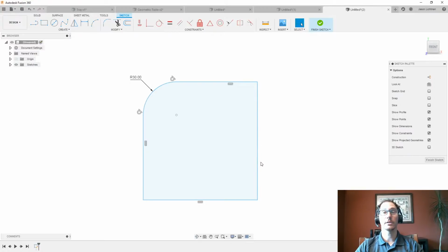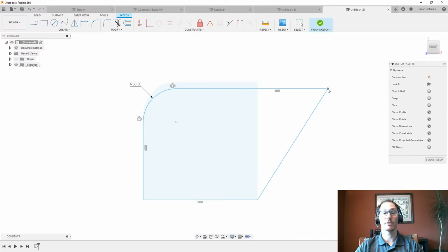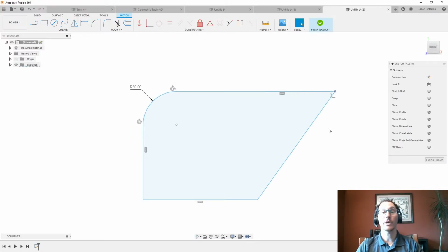Once it's deleted, the geometry itself isn't fully defined anymore, and now you could go and modify it. So once the horizontal or vertical constraint isn't there, now we could go and pick an angle for that geometry. You could do some pretty cool stuff here.